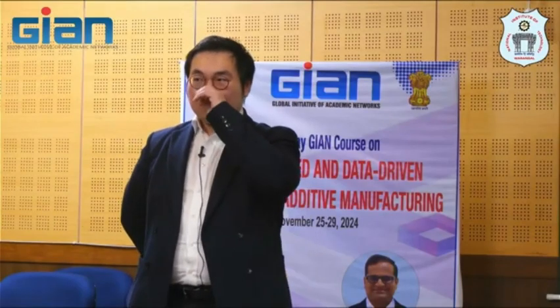We call it print soft, and then we recover the strength later, or harden later. At the time of printing, it is solid solution. It can cause cracking, right, if gamma prime is precipitated at the time of printing? At the time of printing, if it's solid solution, probably less likely.